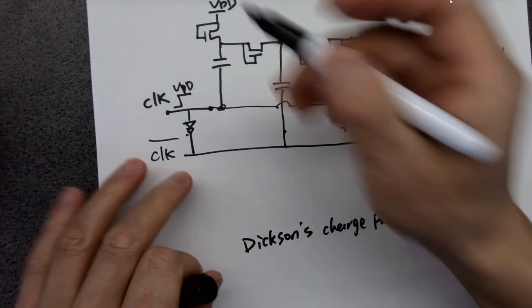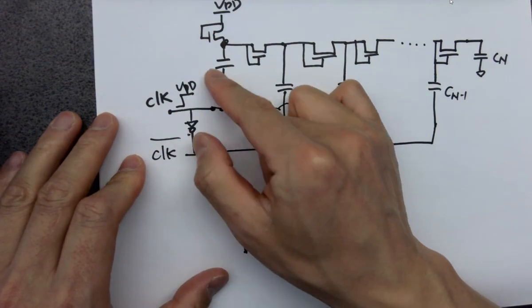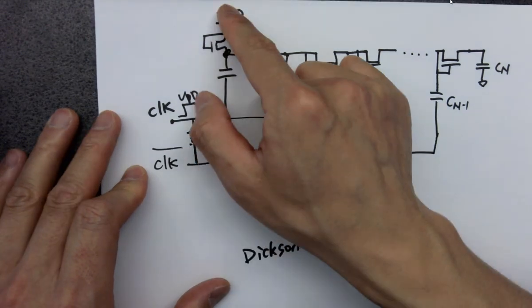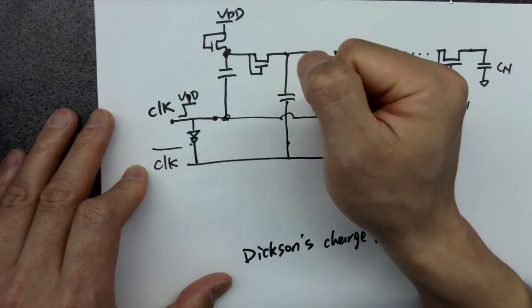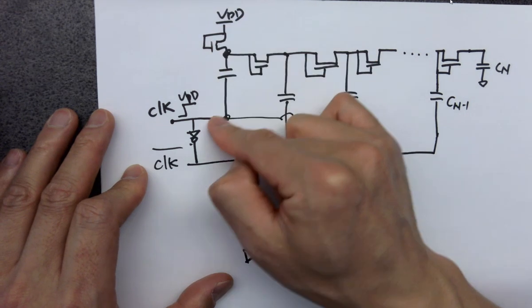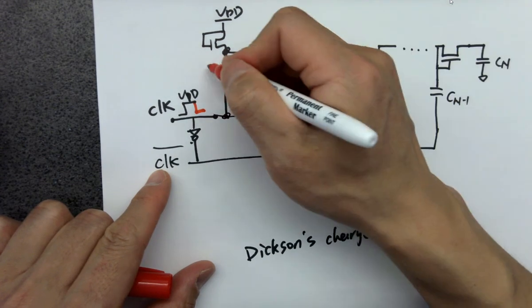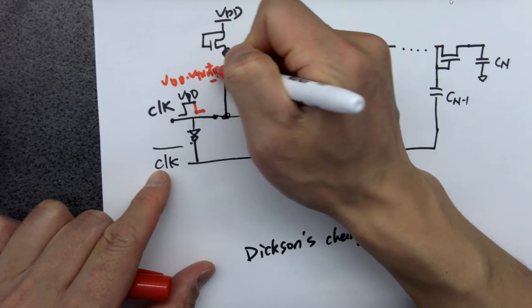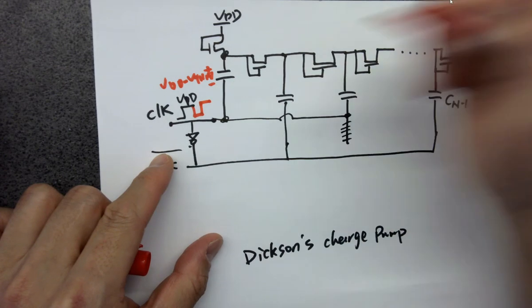So what's the voltage here first? Charging and discharging, right? So when it's pulling, what's going to happen? Boom, charges flowing down. It's like a waterfall, right? When it's pulling, you're getting what? VDD minus VTHN. Okay? And then charge up.